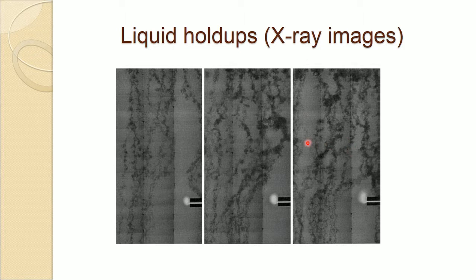So, this is one picture of that, where the liquid flow is coming from the top mimicking the iron and slag, and gas flow is coming from the tube from the side as in the blast furnace, and a raceway is formed, and one can see how this liquid shift is occurring. So, it is going away quite a lot, and one can see also quite a lot of liquid holdup. In this one, one has used water. So, the density difference is quite a lot.